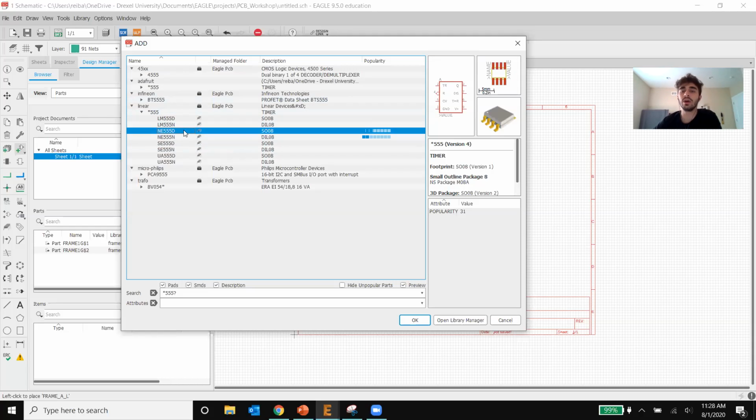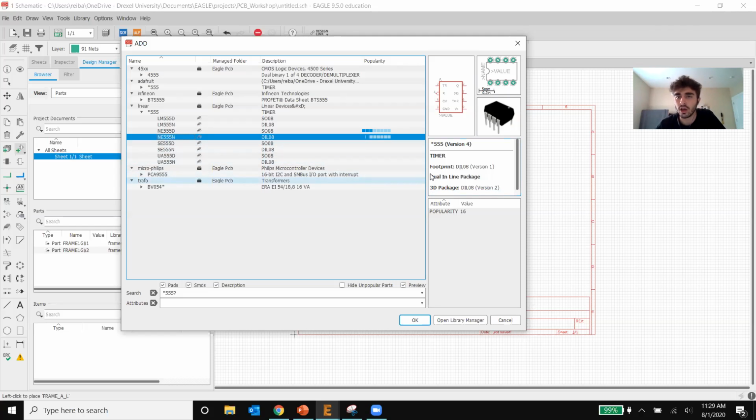But you can also have something like this. As you can see, this is called surface mount, SMD, so a surface mounting pad, basically. These ones are mounted differently. These are not through hole anymore, so we just have pads. Some people choose to use this because they'd rather not have holes in their PCBs. If you want to be advanced, sometimes people choose different options for thermal issues. Today we're going to go with a through hole pad.